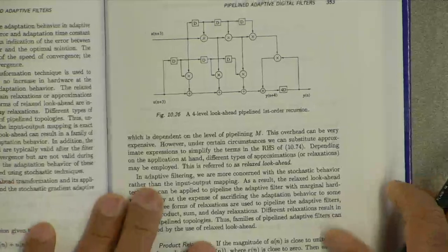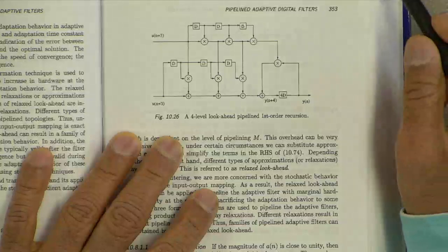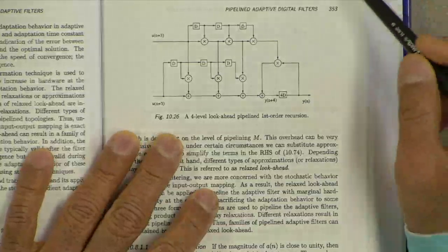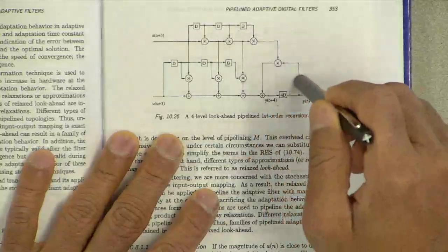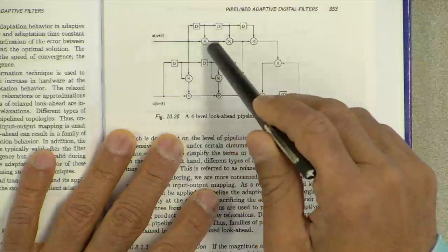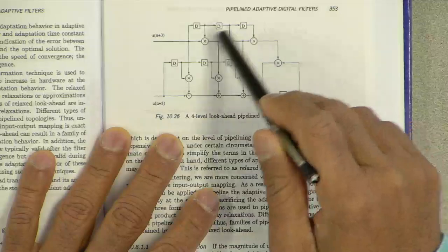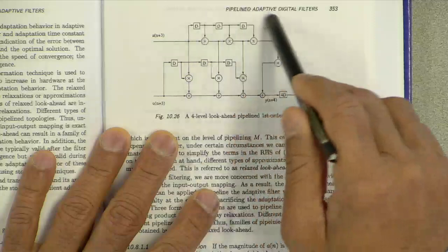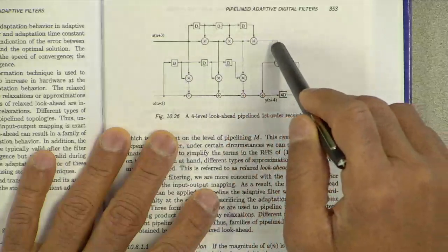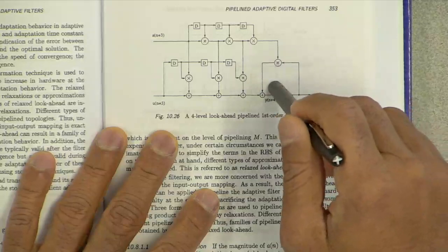So if you look at what that equation looks like in terms of the structure or the block diagram, the coefficient that I talked about as part of the feedback loop, a(n+3) times a(n+2) times a(n+1) times a(n), so that product term of 4 quantities, in this case 4 things being multiplied together, is going to be input to that multiplier as part of the feedback loop.